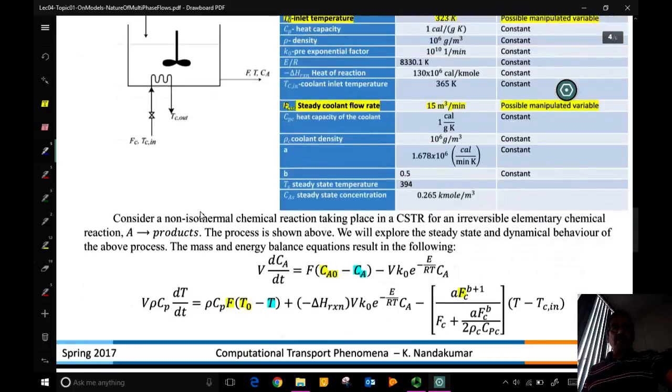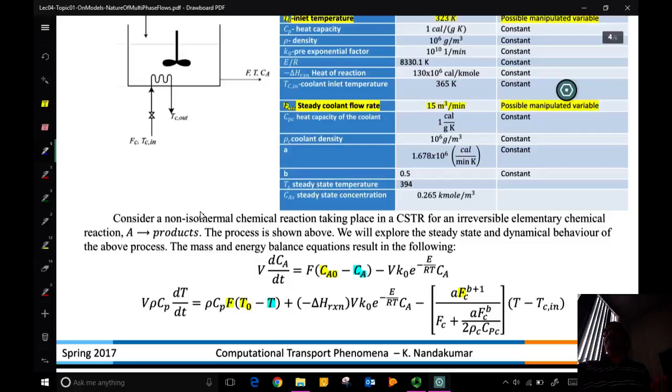If I ask you the question, what are the variables that I'm interested in solving from these two equations? Concentration and temperature are the dependent variables. Time is the independent variable. It is a transient, dynamic, lumped model in our classification of schemes. So I cannot use fsolve to solve this particular problem. I can use COMSOL, and COMSOL 0D will still work because I've ignored spatial variations.